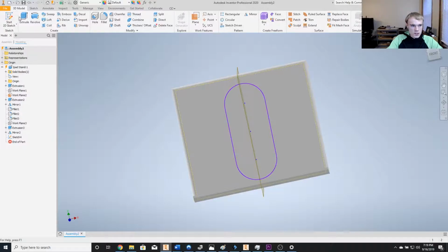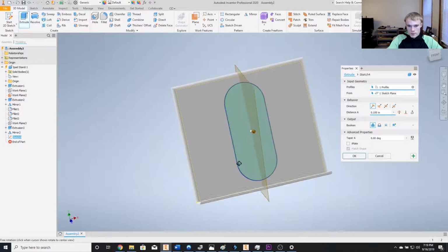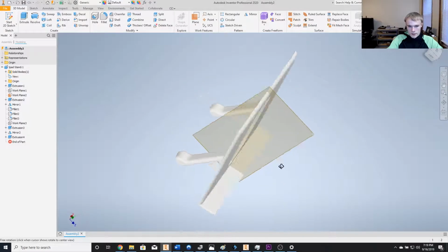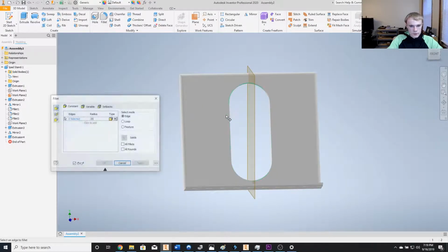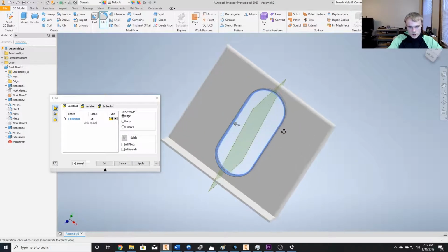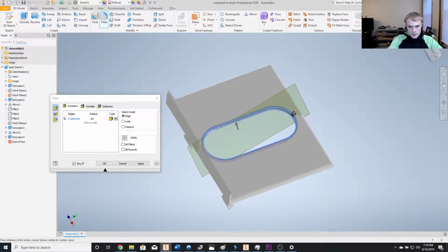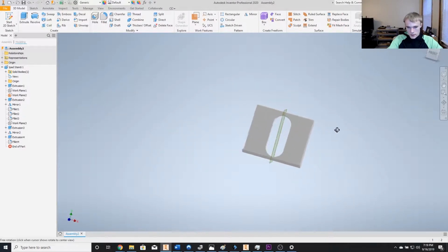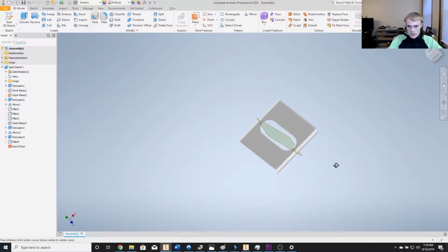The finished sketch, we're going to extrude, and what we're going to do is we're going to select delete, cut, and then we're going to go through all. Okay. Now it's about perfect. We're going to go through, make another fillet. I feel like I'm probably saying that wrong, so, you know, just call me an idiot, but that's probably true. Okay. There we go. I think that'll probably end up being our finished project. Now let's move on to actually 3D printing it.